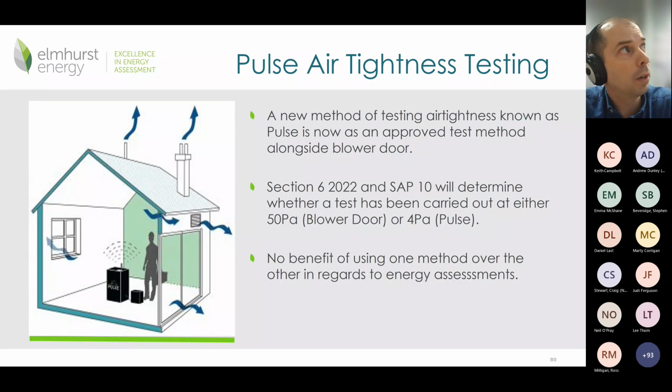That's done at a pressure of 50 pascals, which is pretty high, and it's certainly not reflective of what you would live in, but it does stress the building envelope, so it's a good check to make sure there isn't any leakage where there shouldn't be.